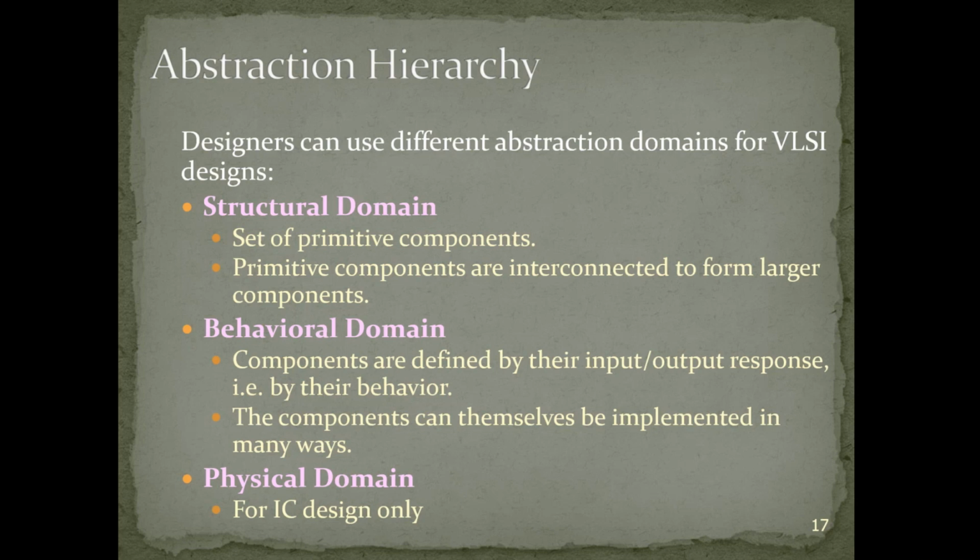And then finally, the last fairly common domain is the physical domain. This is only meant for designing integrated circuits and is not something we're interested in. I'm just mentioning it here for completeness. So generally, as far as our VHDL designs will be concerned, we'll be operating either in the structural domain or in the behavioral domain. So we'll be employing those two strategies really. Mostly behavioral, but structural is possible as well.